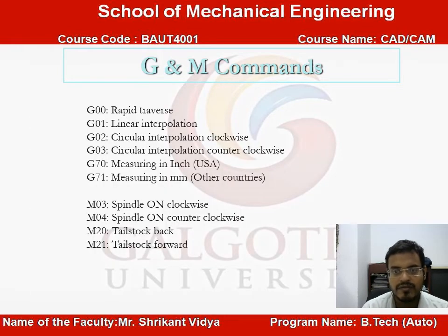So, G and M commands. There are different commands like this. Suppose G00 is rapid traverse, movement in air. G01 is linear interpolation. These are holding commands also: after G01 is made active, G00 will be deactivated. In the same way, if you write G02 in the next block, G01 is deactivated. These are the basic commands which are very important to remember, also from the competition point of view.